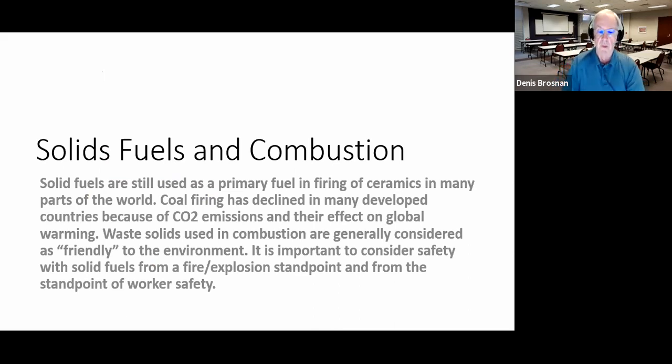in ceramic kilns. Wood and later on coal, when it was available, used in lump form or large pieces of wood. In today's world, we use pulverized fuels, fuels that have been crushed or shredded so that we get different handling systems. We don't use stoker systems or burners where lump coal is injected into the side of a round kiln, for example. We are crushing the material and pneumatically injecting it into the kiln, as you will see today.